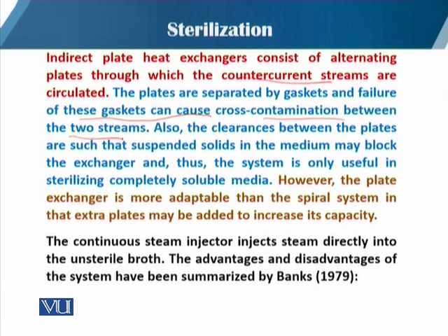The plates are separated by gaskets, and the failure of these gaskets can cause cross-contamination between the two streams. Also, the clearance between the plates is such that the suspended solids in the medium may block the exchangers, and thus the system is only useful in sterilizing completely soluble medium. If the medium is not soluble, then there is a problem.